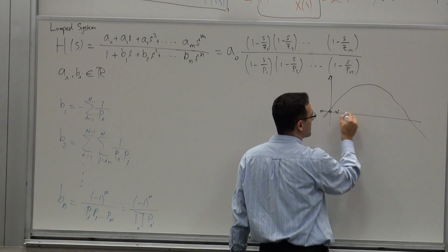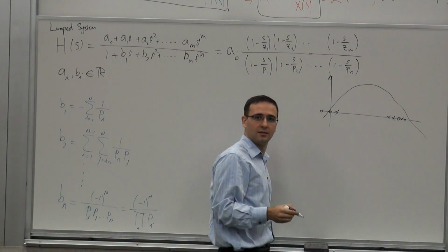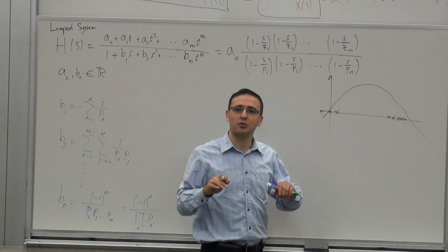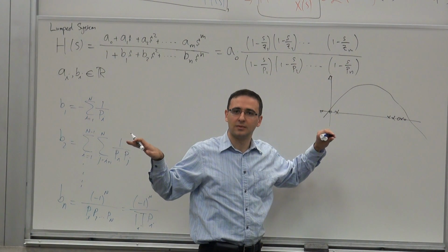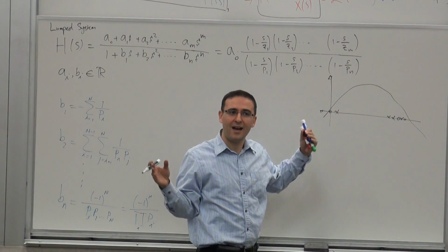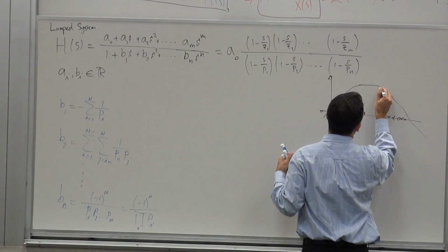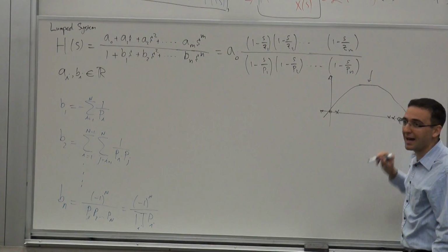Poles and zeros down here, and poles and zeros up there. And what is the gain that matters in this case? What is the parameter that you try to capture that doesn't depend really on the dynamical elements? If you have designed an amplifier that's well designed, then you will have a range of frequencies over which the gain is more or less constant in the midband, right? It's this gain that matters.